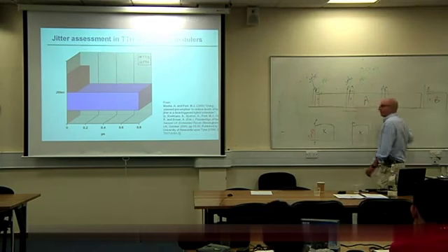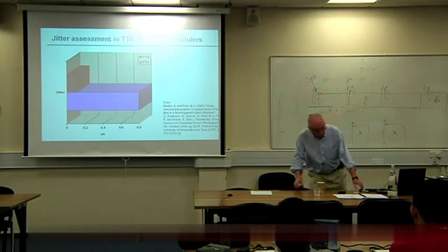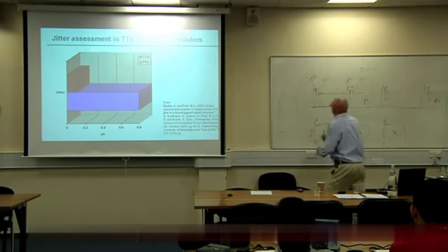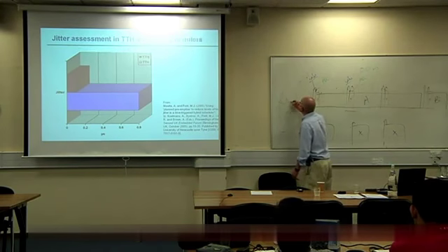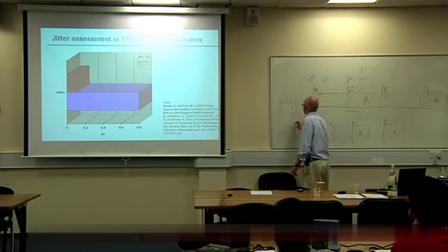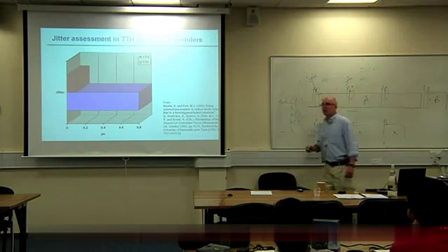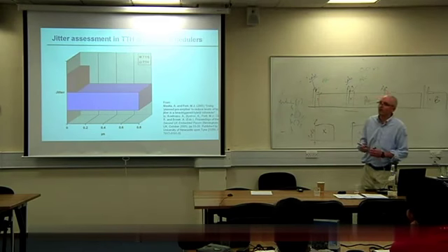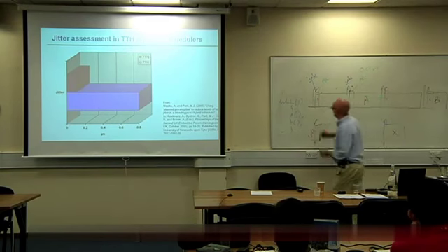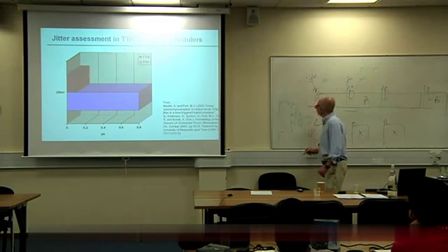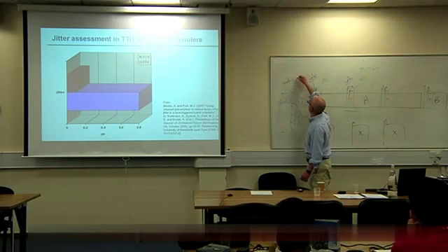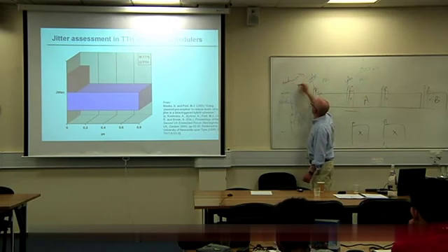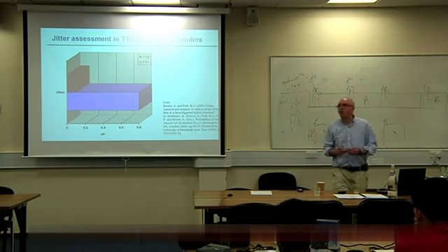There are lots and lots of these systems running. Sometimes what people do is they run versions. That's a very common form of simple hybrid scheduler. So that's running in our while one loop, and then we've got our interrupts every millisecond or something.